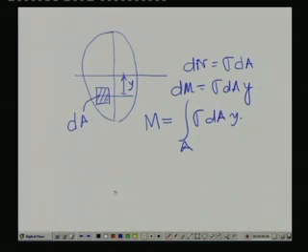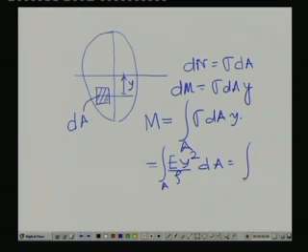So, if we substitute the values of sigma dA into y, then what we get? Sigma was coming out to be what? It was coming out to be E y by rho, integral over the area A. So, this comes out to be a square term, multiplied into dA. So, that comes out to be the integral over the area of y square dA, and I missed this one. So, this should be E by rho.